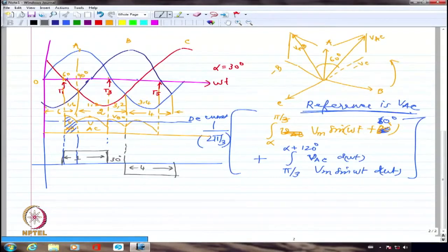In the other fully controlled converter, because we had symmetrical conduction of each of the positive and negative devices, I had 120 degree current in the positive, 60 degree of zero current interval, again 120 degrees current in the negative, again 60 degrees of zero current interval. So it was separated very nicely by 60 degrees, or symmetrically.